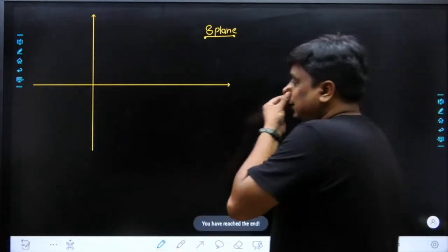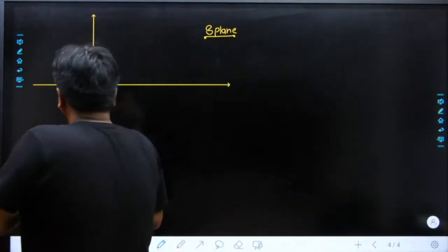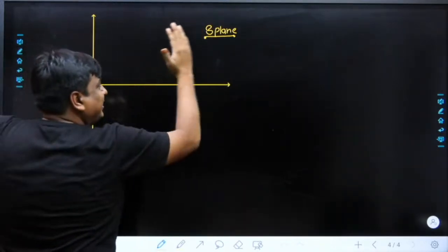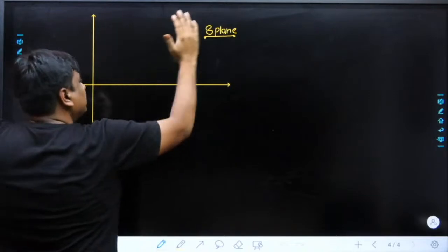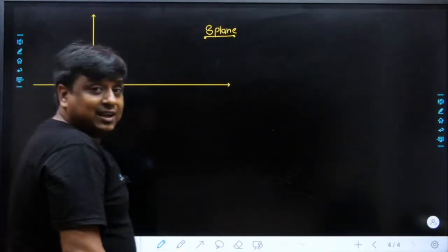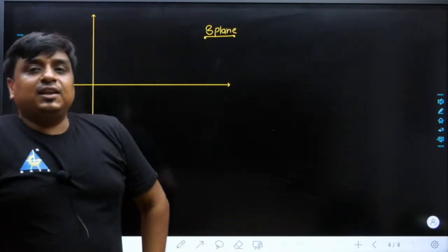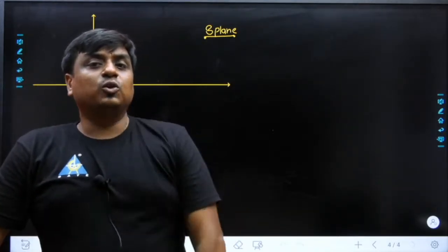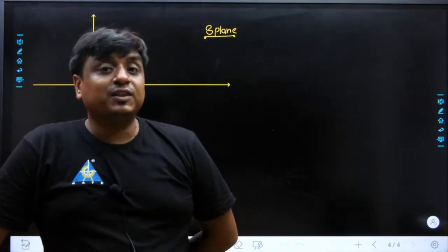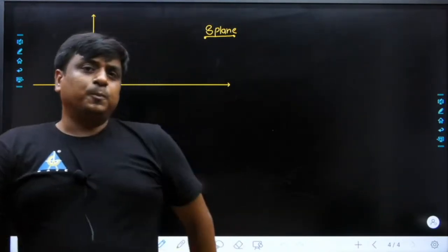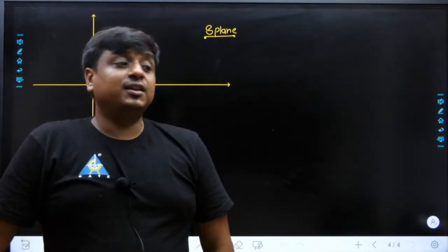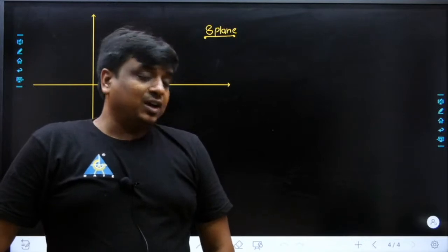Now we are playing smartly. We are going to encircle all of the poles and zeros which are towards the right hand side of the S-plane. Many of the students would think, sir, what is the need of it? My dear friend, there is a need, and that's nothing but stability. In case of a stable system, all of the closed loop poles have to be towards the left hand side of the S-plane. If any closed loop pole goes towards the right hand side of the S-plane, that's done, the system becomes an unstable system.